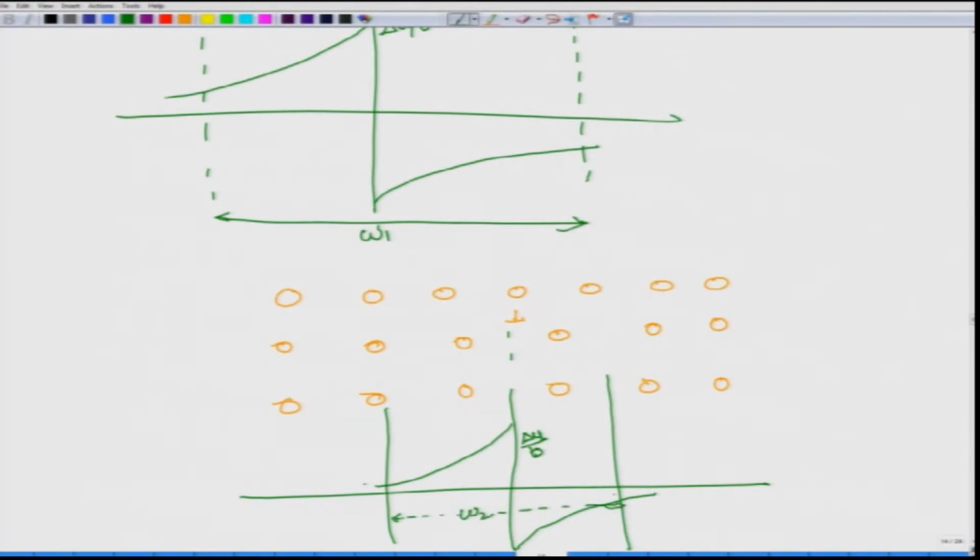So, what we see here is that clearly W1 is greater than W2. Now, the width of this dislocation is larger, the width of this dislocation is smaller, and because of this their movement would be severely different. They will be completely different in how the dislocation moves, so this has a wider core, this has a narrower core.